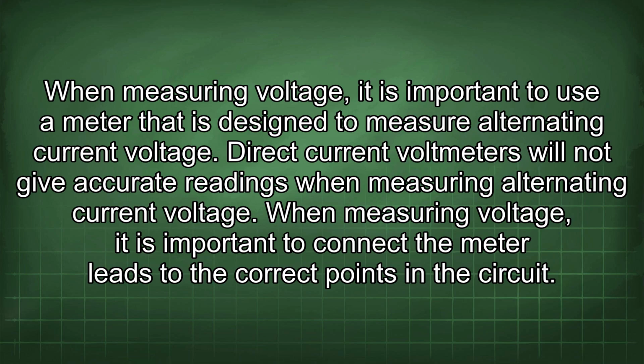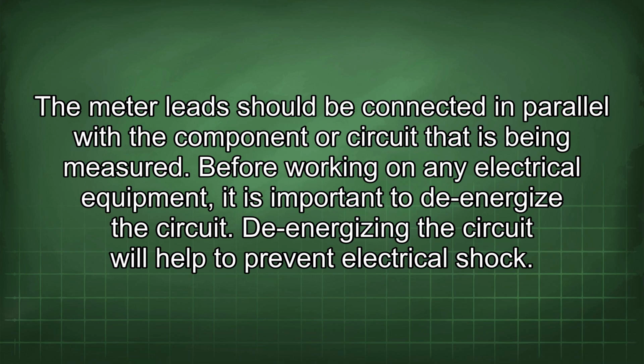When measuring voltage, it is important to connect the meter leads to the correct points in the circuit. The meter leads should be connected in parallel with the component or circuit that is being measured.